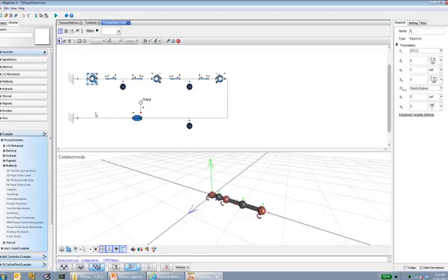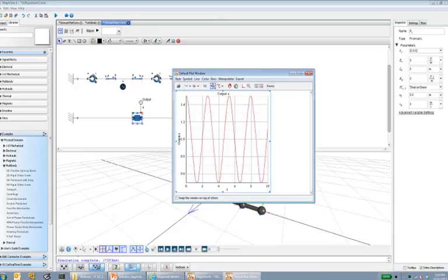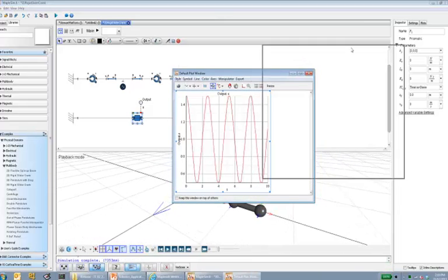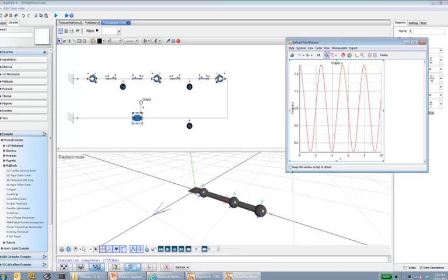You can see the revolute joints. Three of them are here, and we also have a prismatic joint, and together they create a slider crank mechanism. The simulation is done the same way as our single pendulum example, and we have a probe for the position of this prismatic joint, or the displacement of that point, and we can see the animation of the resulting motion as the action of gravity. So this is a simple relationship between the components.